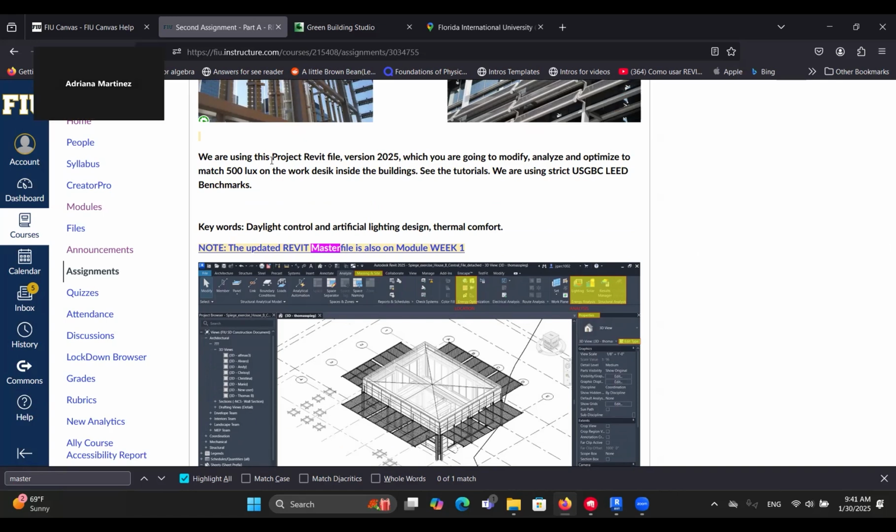I just want to know if we had already set up the true north. Like when you turn on the solar path, is that at the north? It seems correct, but I just want to make sure. Once you set up the location, you should be fine. Because before the analysis, you're going to be prompted if you want to use the specified location, or a geographical location or something like that. You want to use the specified, and if you did the coordinates correctly, then you should be fine for this part.